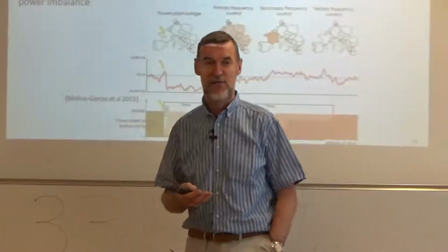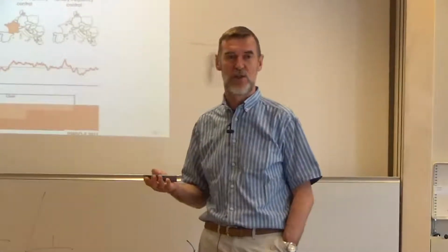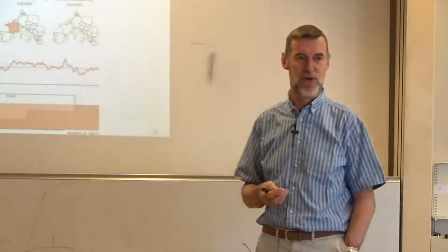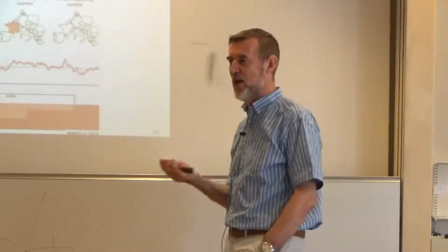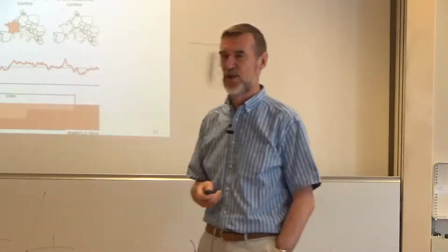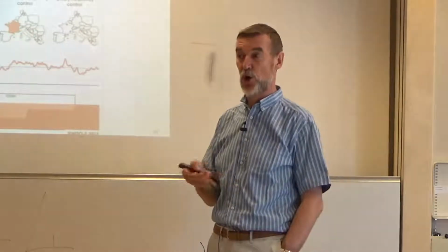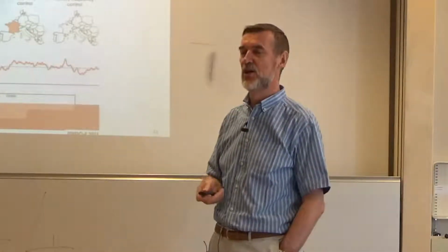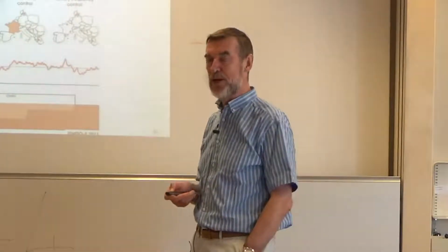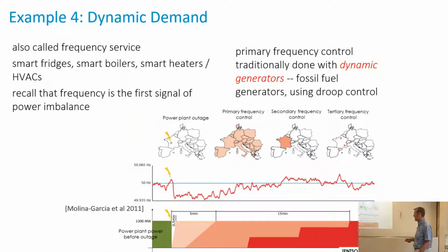Most blackouts we have, like the one we had a few weeks ago, are due to distribution network. A short circuit somewhere on the line, an insulator that has a problem, a transformer that has a loss of something somewhere. So those are local blackouts that may kill part of a grid, but complete blackouts that bring down an entire country are extremely rare. The last major one was Italy in 2003, so 16 years ago, where the whole of Italy was disconnected from the grid, but that's extremely rare. And the reason it's rare is because of this system here.